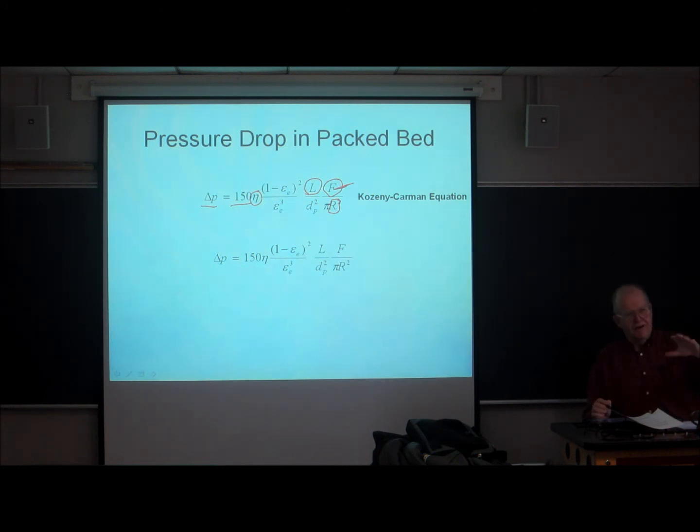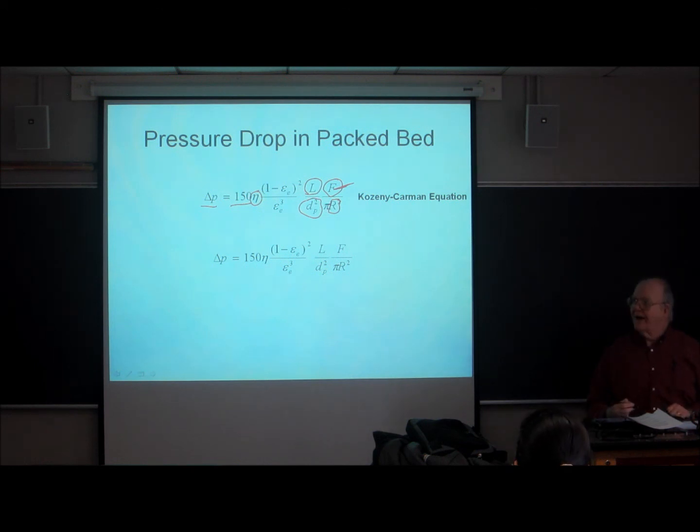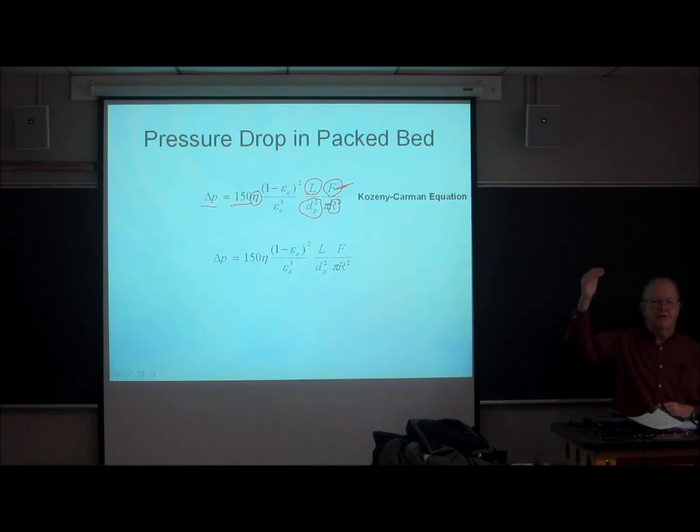It's not the flow rate, it's the linear velocity that matters. And here's the kicker. It depends inversely on the square of the particle diameter. Now, over the history of LC, the particles have gotten smaller and smaller and smaller.